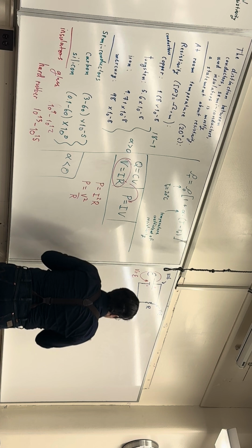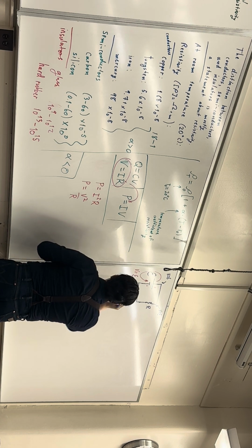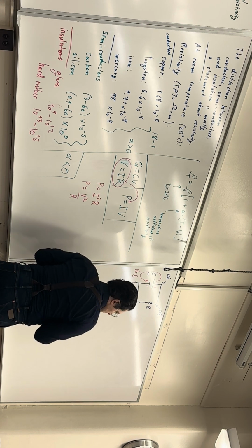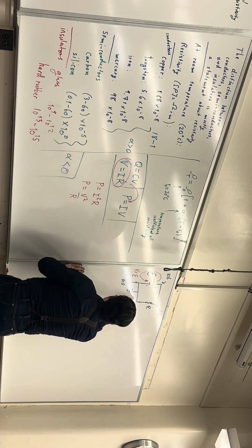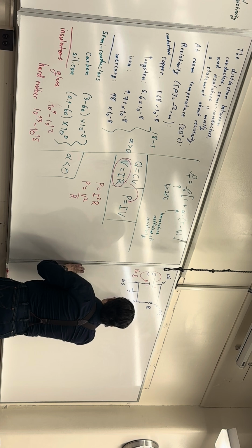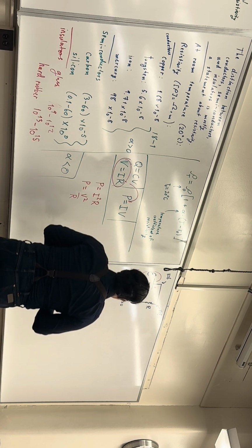And just for simplicity, let me ground the bottom here. That grounding just means that I'm setting this voltage here to be exactly 0. It's harmless. It's very easy to do that just so that you have a reference point. And that means this voltage is also 0, because this wire has no resistance, so there can't be any voltage drop.